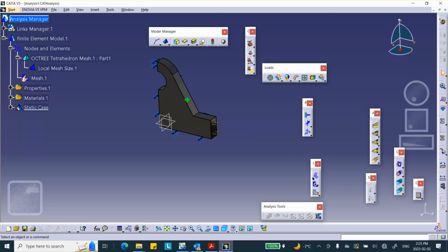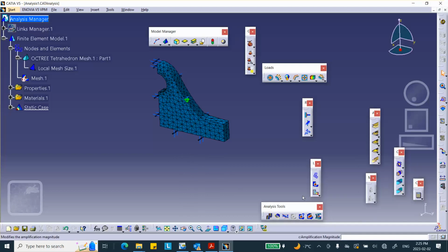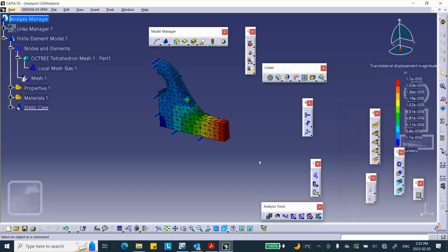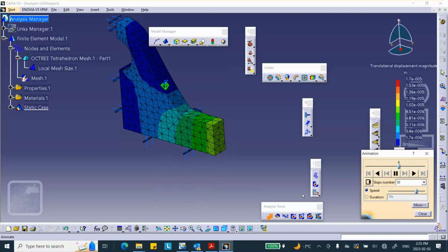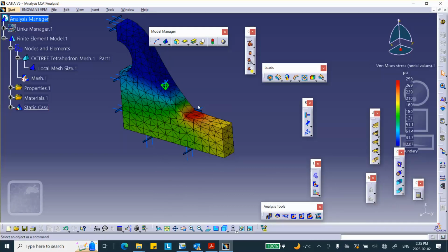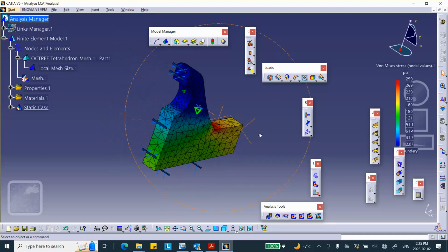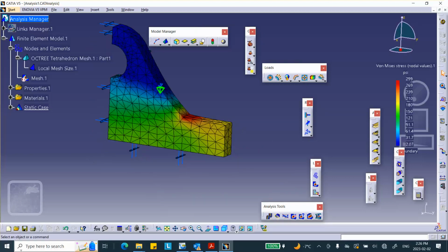That's pretty much it. So if you look at the deflection, it is what you expect, right? It is what you expect. If you want numbers, there we are. Needless to say, when you put a pressure here, it's going to elongate. You can see that. And if you want the Mises stress, the biggest stress is in this area, but if there's a fillet here, it's going to be reduced. These are very low stresses anyway. So that's pretty much it. I'll take care of activity number 4. And there's one more to do, activity number 5.